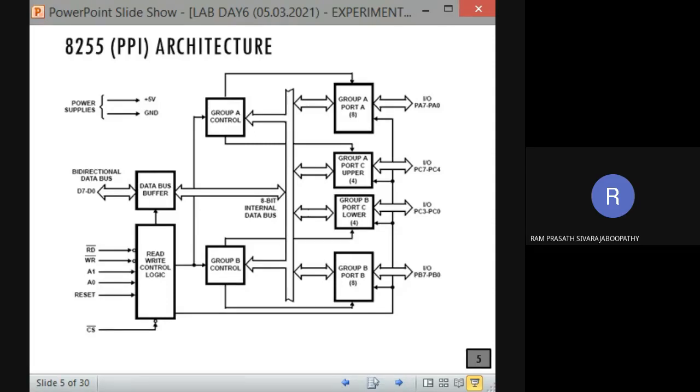See, in total we need an 8-bit address. During the ready signal operation, you have learned this. Yes, Shivakumar, obviously what Shivakumar said is correct. Already, when we taught the ready signal, we explained this concept. So for chip select, what am I going to do? Using that 8-bit address, A1 and A0 are connected directly here. The other 6 bits are used for chip selection. Yes, very good Shivakumar.